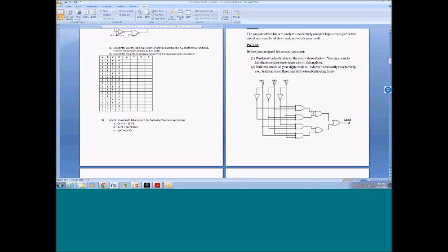So I tell them, you've got these little intermediate states. Once you wire this thing up, test this, make sure it's working right. Test this one, test this one, test this one. Then, if you know all those are giving you exactly what you expect, and something's not working right, it's probably got something to do with this little OR network that you have, and then you can troubleshoot where it is.